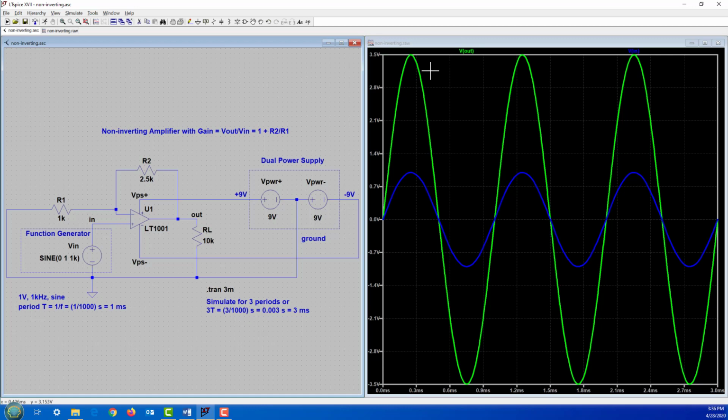You're just going to change R2 and run the simulation, right? And then copy both the schematic file and the waveforms to show us that you've done the work. Very simple, as before. And I hope you guys know how to copy and paste, right? You just see there are 2 windows. You can highlight 1 or 2 of the windows. So you can highlight this window, for example. Let's say Tools, copy bitmap to clipboard, right?